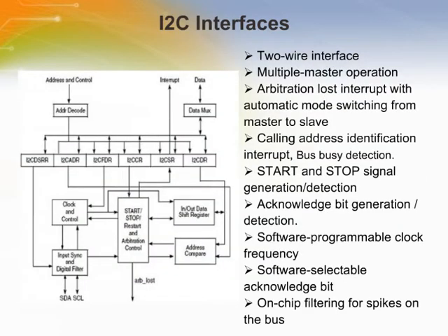The 2-wire I2C bus minimizes interconnections between devices. The synchronous multiple master I2C bus allows the connection of additional devices to the bus for expansion and system development. The bus includes collision detection and arbitration that prevents data corruption if 2 or more masters attempt to control the bus simultaneously.